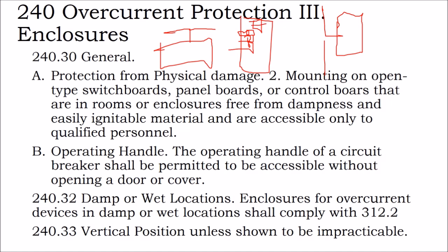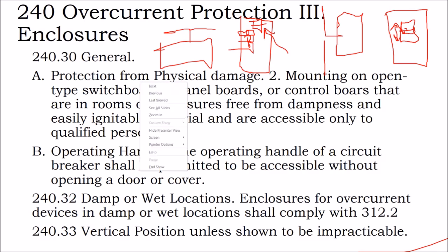So that's what we're saying, is that wherever this switch occurs, if it's possible, that should be in an up and down location. So if you have a box with a single pole in it, but they still want you to put a breaker box there to be used as a system disconnect, as an external disconnect, that's just not a knife switch. A breaker box is cheaper, so you get a breaker box here, and then you have a switch that can kind of go up and down. You can't put that switch on its side if you can otherwise locate it so that it toggles up and down. So your switches go up and down.